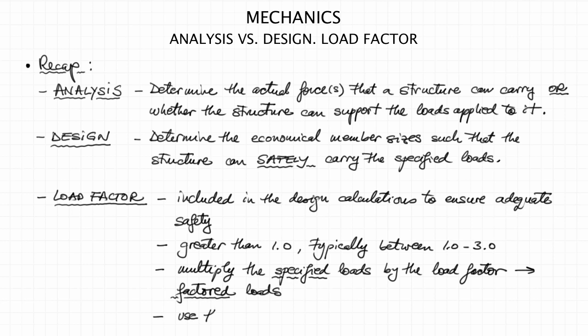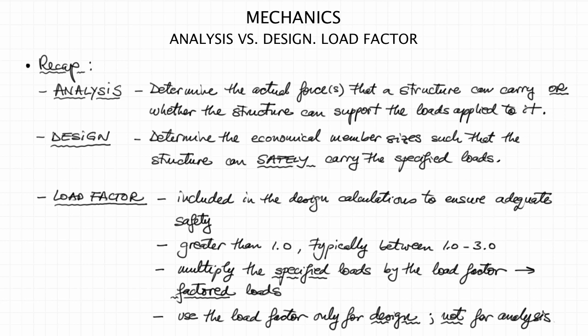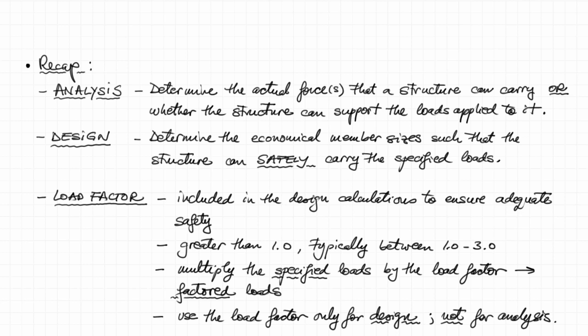Because the design operations are the ones that need to have this additional safety included, we use the load factor only for design. We do not use the load factor for analysis problems. So only in design problems we should multiply the specified loads by the load factor to obtain the factored loads and use them in design.